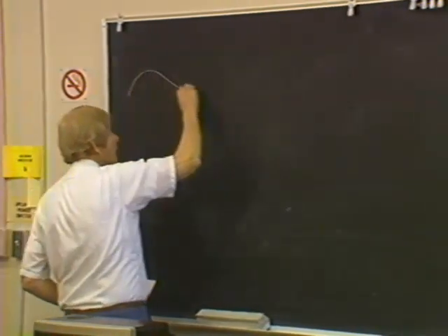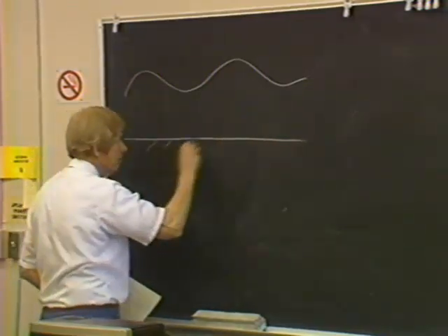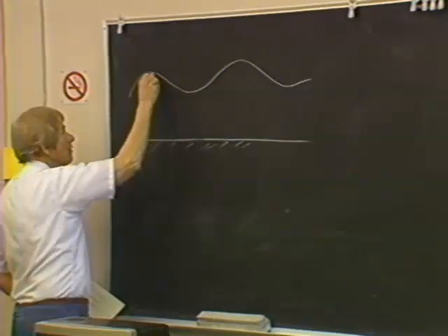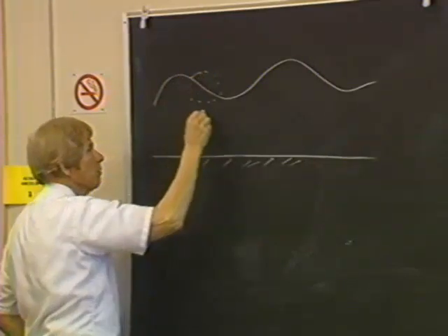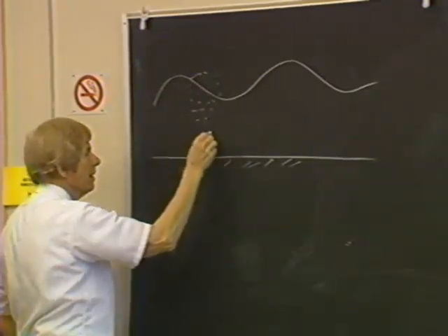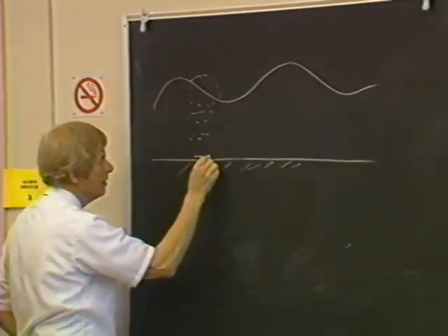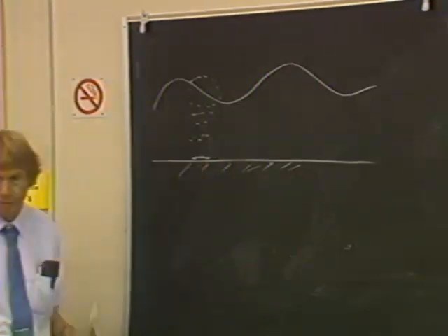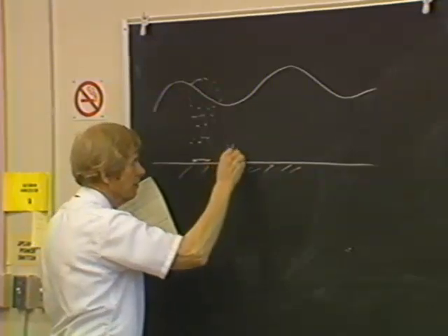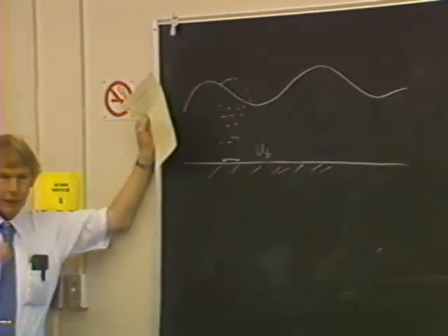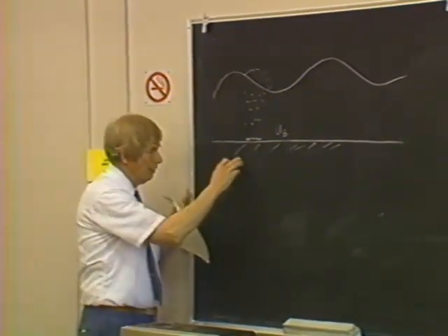Well, recall we were talking about shallow water waves and the fact that the orbital pattern was something like this, and just back and forth near the bed. Now, when I say near the bed, we'll call that the velocity u sub b. Near the bed, that's really at the top of the viscous layer in a hydraulically smooth bed.